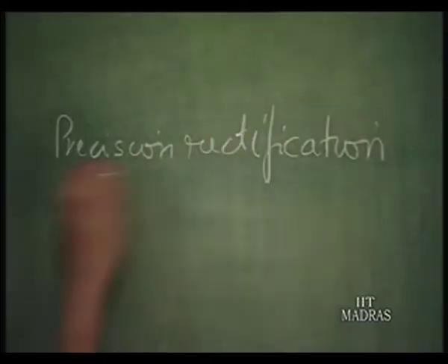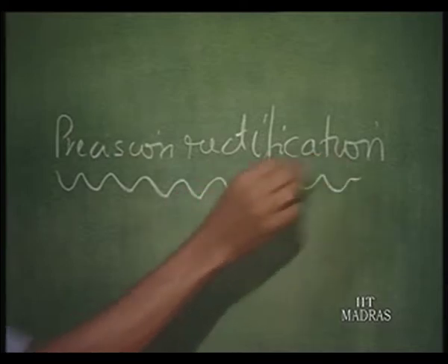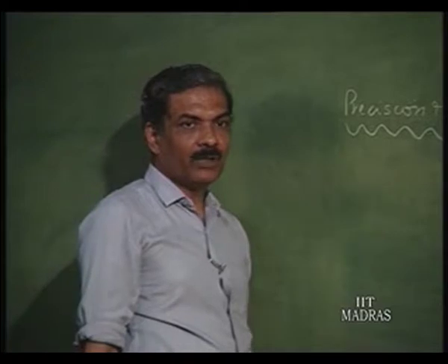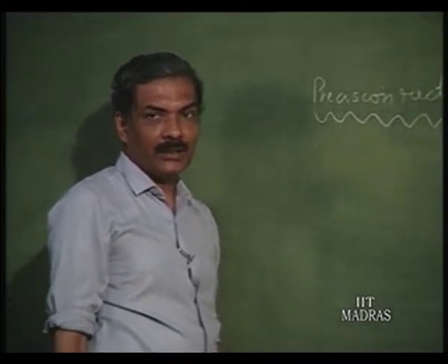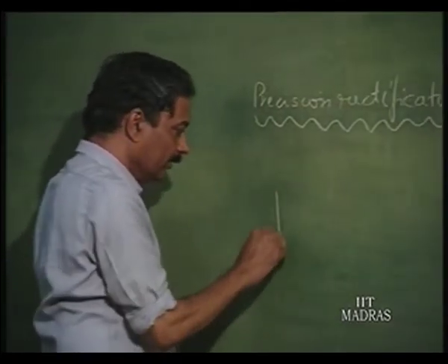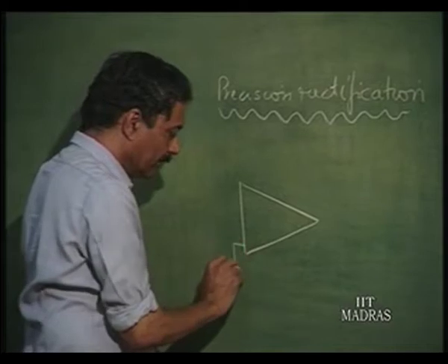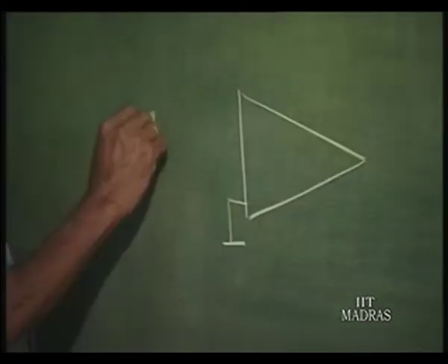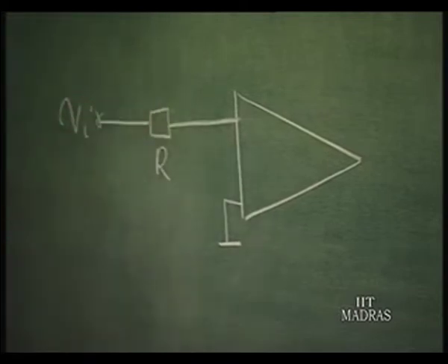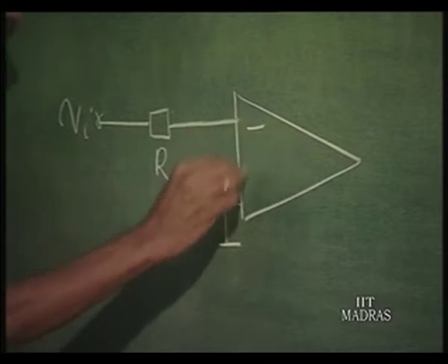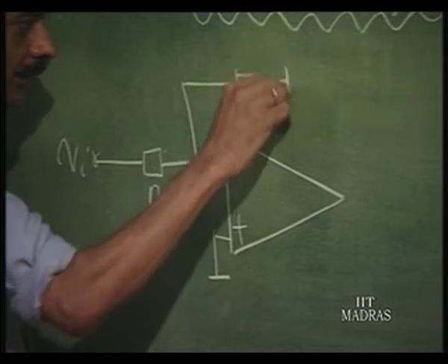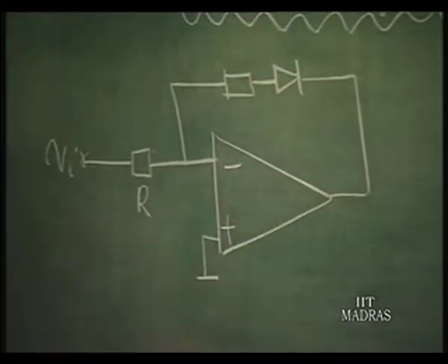using op amps. We had seen this phenomenon in the removal of distortion, crossover distortion in class B amplifiers using op amps. Same thing, we can use the same principle of feedback. I have a resistance here which will convert the voltage into current, okay. Negative feedback therefore is going to be made available through a resistance where the diode conducts.